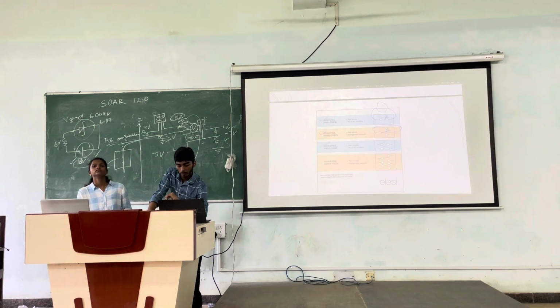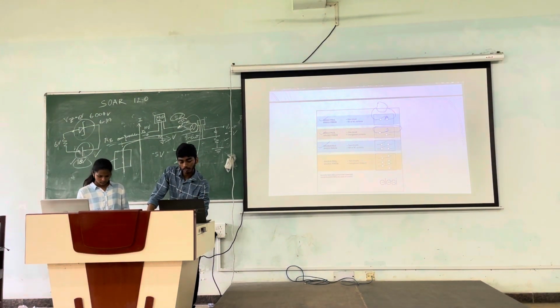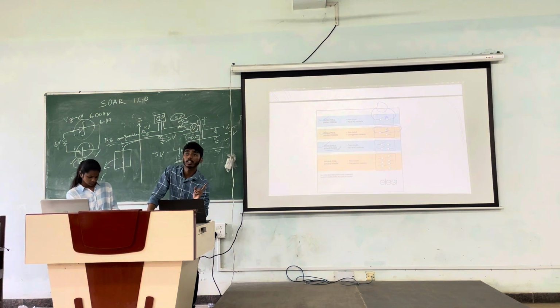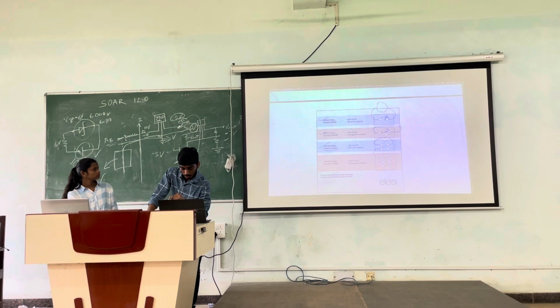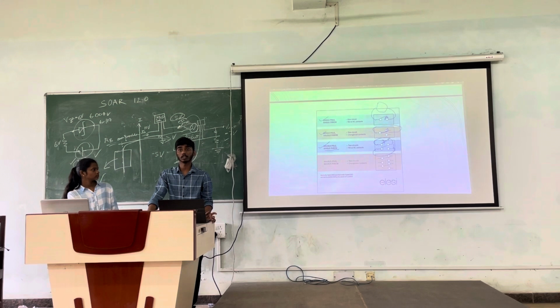Okay, now double pole, single throw. As the name suggests, double pole means it can control two circuits, and still we have single throw. That means it has one contact point only. Okay, so we have two terminals at both the sides. So we can control two circuits simultaneously, but still you can see that if this toggle is at this position, like if it is turned upward, it is not getting connected to any terminal. Okay, similarly this bottom toggle is also not getting connected to any terminal. You guys might have this confusion that it is connected to this, but it is not.